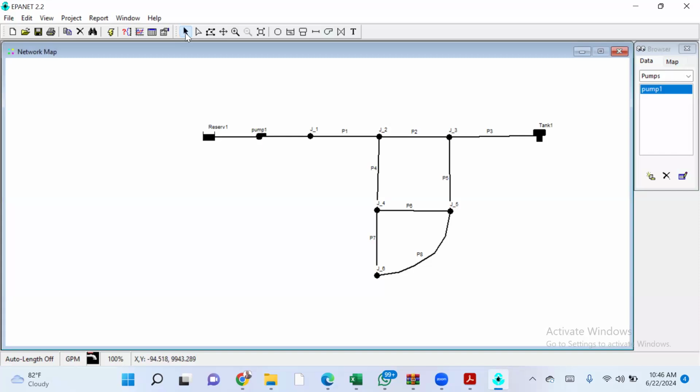So please, can you come again for adding vertex? I can't get it, sir. Okay, first of all, you highlight the pipe where you want to put the vertex. Once you highlight it, the vertices will show. You now go here and click on vertex. Look at the word vertex. Once you click on this vertex, you come back again, right click and say add vertex. You must click it two times. The first one will not show, but the second time it will start showing.